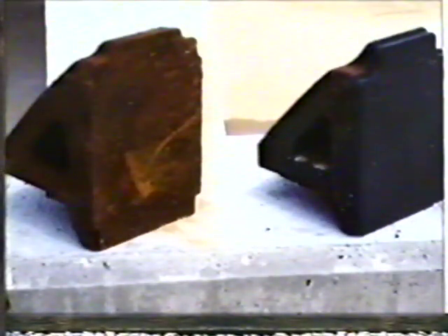The next event in the gauge spreading derailment scenario was truck warping. What caused the truck to warp? Several factors affect a truck's resistance to warping. First, a significant part of a truck's warp restraint comes from the snubbing wedges. Snubbing wedges, which slide easily, lower a truck's warp resistance. Factors which decrease snubbing wedge pressure include wedge wear and snubbing spring damage or fatigue.